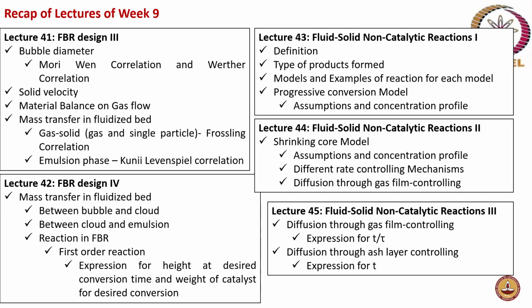And then the week 9 lecture included discussion on fluidized bed reactor and also fluid-solid non-catalytic reaction. Under fluidized bed reactor, the Mori-Wen correlation and Werther correlation for bubble diameter, solid velocity, expression for solid velocity, and then material balance on gas flow and mass transport in a fluidized bed reactor.